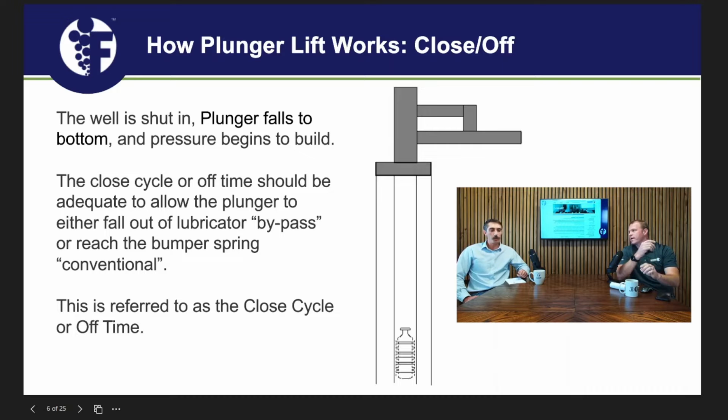Well, we're shut in, so you could do casing pressure build. You could do tubing pressure build. You can do what we call load factor, which is a differential between the two of those. You can look at line pressure even. There's just so many ways. But it's good to note that time is not the only function to do it on.